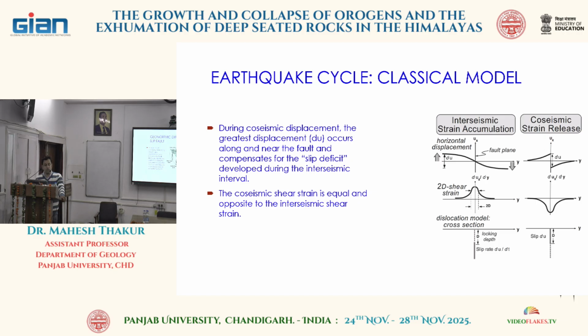In the Himalayas we have a lot of vegetation, and sometimes the strike of that also creates an impression that there is some kind of linear feature, but most of the time these are just the bedding planes of the rock. So in the Himalayas it is sometimes difficult to find the expression of an active fault. In that case we have to rely on different geomorphic markers, for example sag ponds, if you have a chain of these ponds in a linear pattern. And we also take the help of remote sensing.